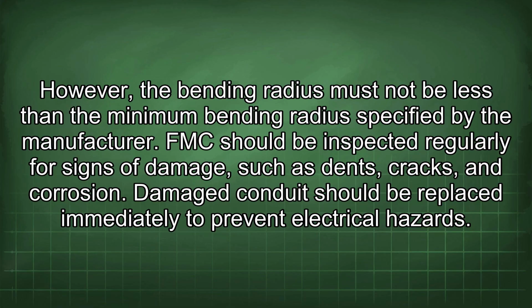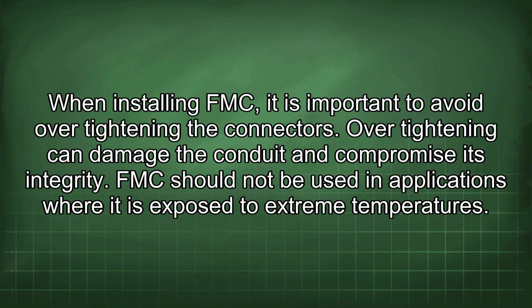FMC should be inspected regularly for signs of damage such as dents, cracks, and corrosion. Damaged conduit should be replaced immediately to prevent electrical hazards. When installing FMC, it is important to avoid over-tightening the connectors. Over-tightening can damage the conduit and compromise its integrity.